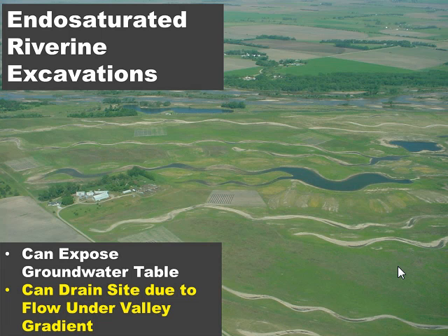and again, for the purpose of actually restored wetland hydrology. And in no instance should we ever take those channel excavations, or those braid excavations, and connect them back with the active channel, because that surface runoff will be drained out of the valley and run directly back into the river.